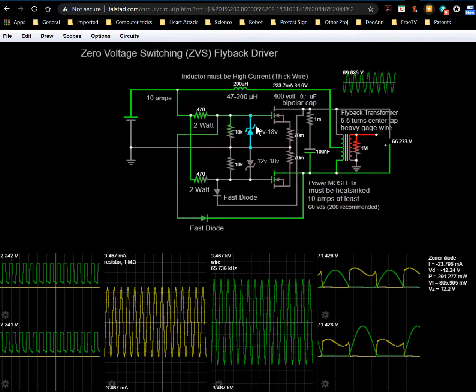It'll have to discharge through this diode through ground, which, remember, since this is still on, it still has ground here. The transistor is in the process of turning off, but it can't turn off until that capacitance is discharged. So until it is, both of these are going to be on at the same time, very briefly.